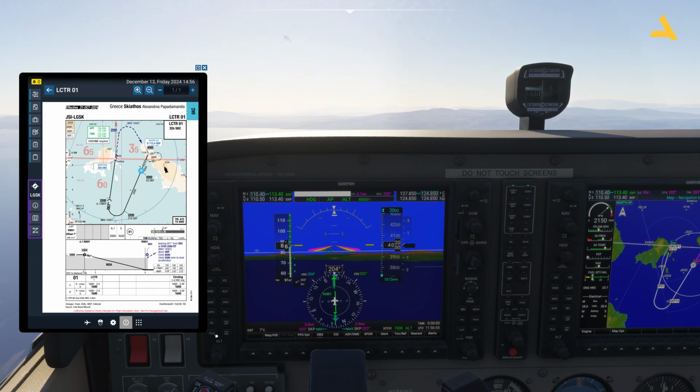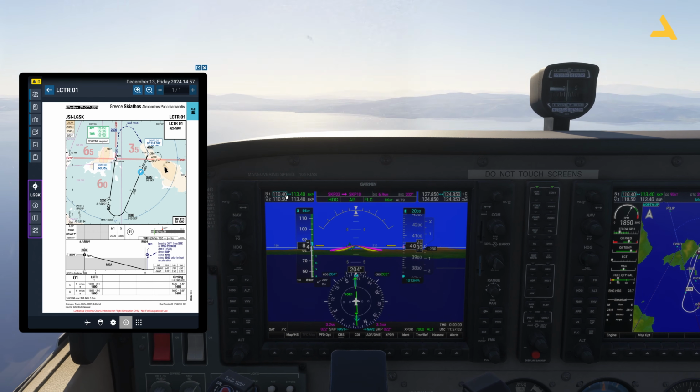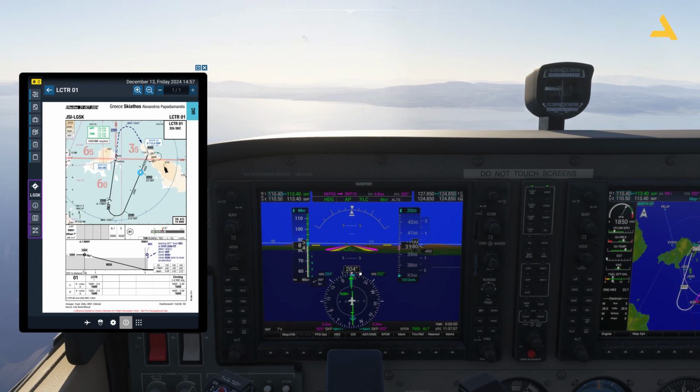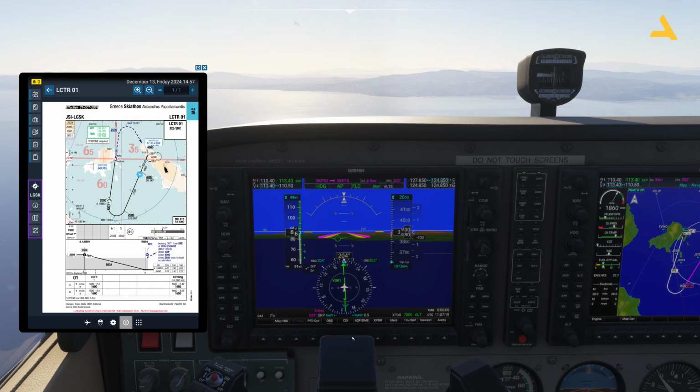So let's further reduce it and use flight level change. Reduce the thrust. Now what I'm going to do is this: I don't need the VOR tracking on both, because for NAV1, I'm tracking this VOR. For NAV2, I can just change it because I want to get rid of this bearing pointer, as now I will be bringing up the bearing pointer for the NDB.